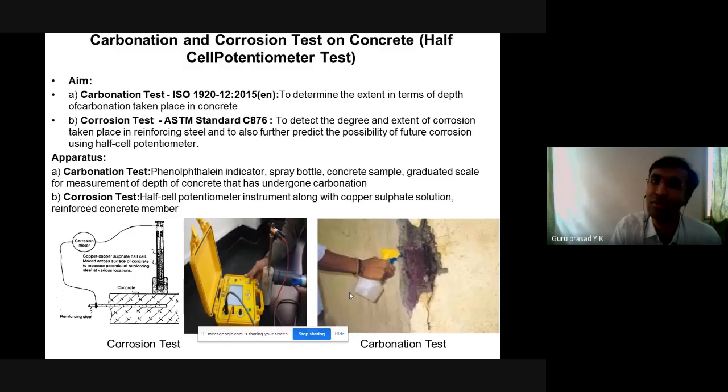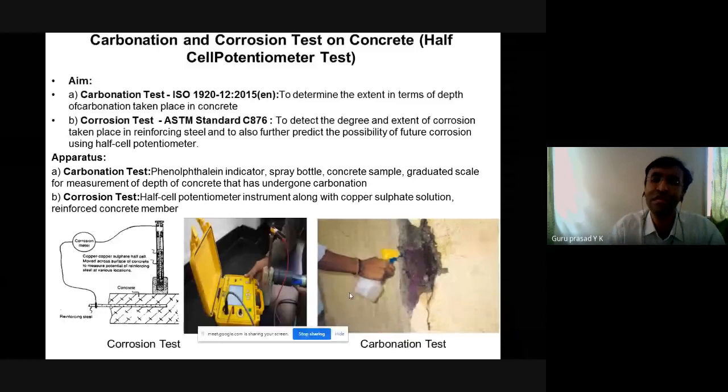All of you would have come across this when you test concrete in the laboratory. You put the cube or cylinder, and when you apply the load, the cracks slowly emerge vertically, and after that you have the cup and cone failure, where the concrete slowly deteriorates by cracking. It is not like glass.